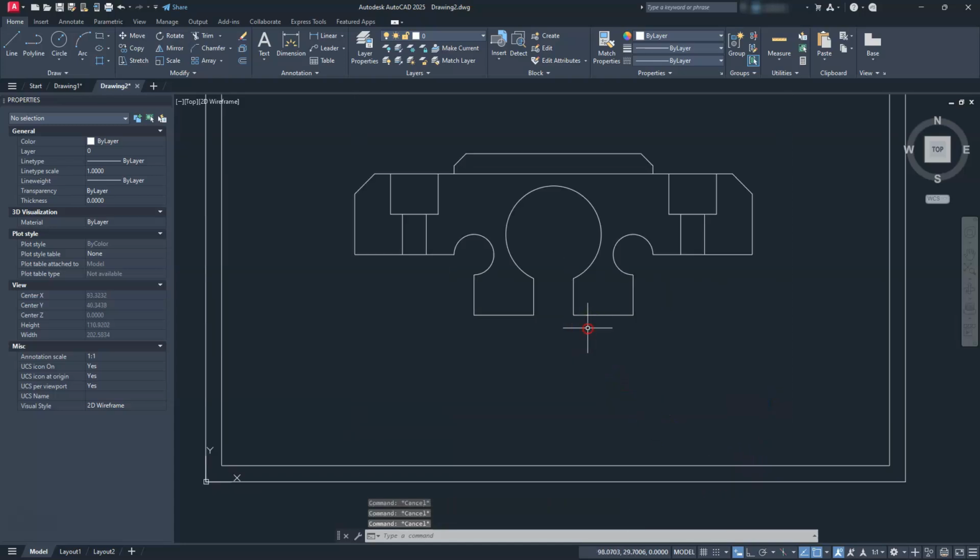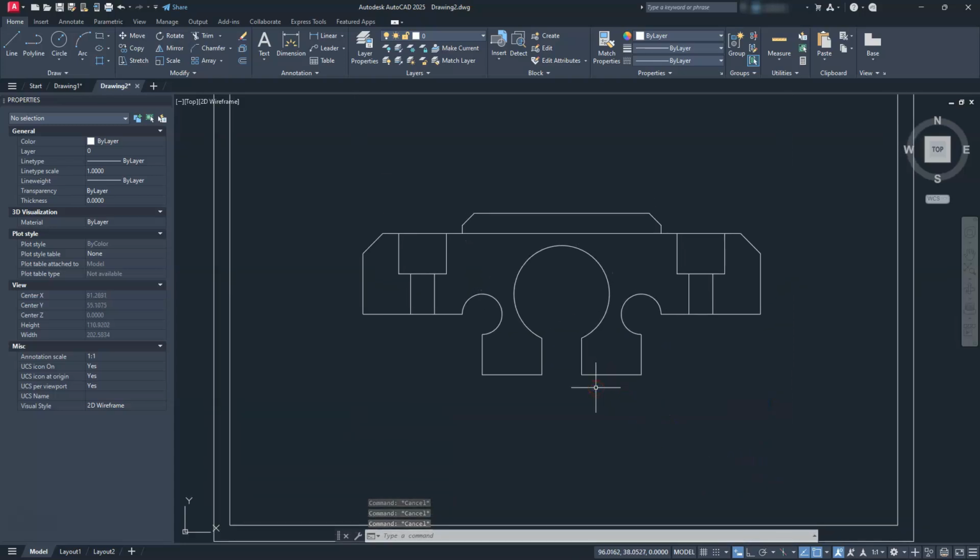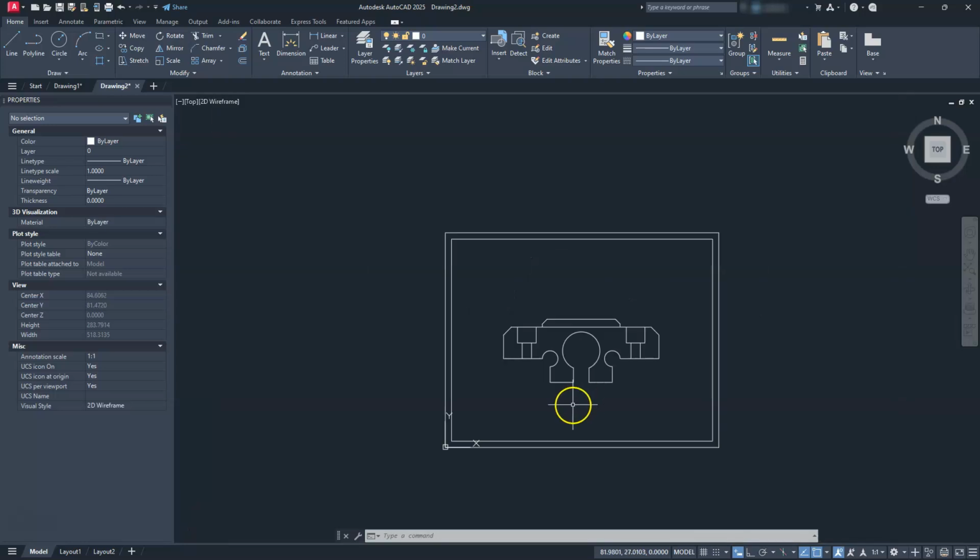And then let's go ahead and take a look at what we have. So now we know that our scale factor is 16. From this point, you're going to have to determine what method you want to use. Now, if you're using paper space, you don't have to put this border around this. Your title block will be sitting out in the layout tab. But if you're going to use the standard or annotation method, you can go ahead and set that now, right?